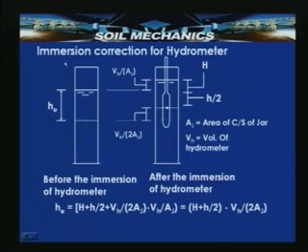So, as I discussed, the hydrometer is required to be corrected for immersion correction, because generally this correction is required after immersing the hydrometer for more than 4 minutes. So, initially this correction is not required, but after elapsing a time of 4 minutes, this correction is required to be implemented.